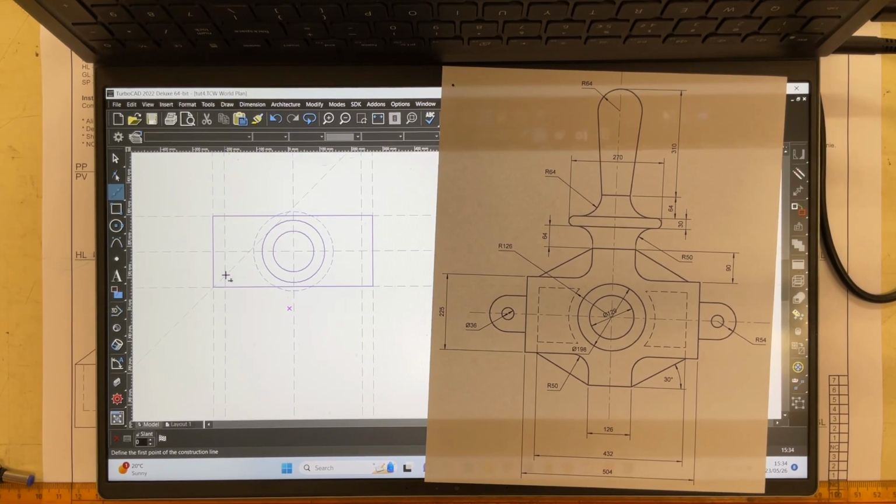Okay, I now have the corner that I need in order to draw in the lines. I'm going to go in over there, click on that, there we go, clicking a line going across there. Once I've got that, I can now draw in another little 45-degree line, going over here, over there, go to that corner over there, type tab, 45, enter, that gives you that construction line at 45 degrees.